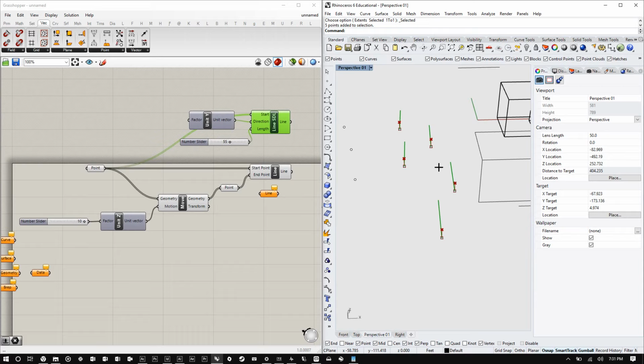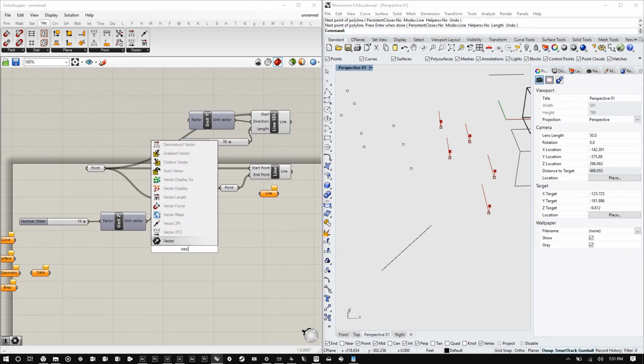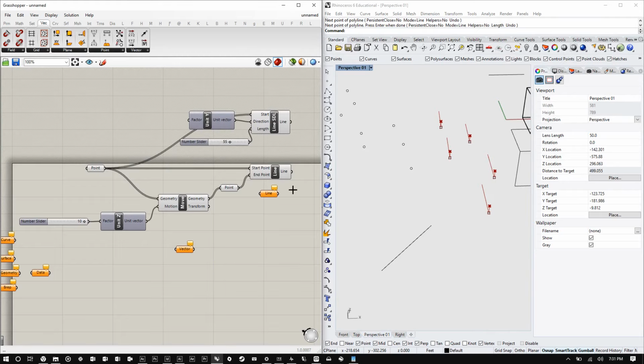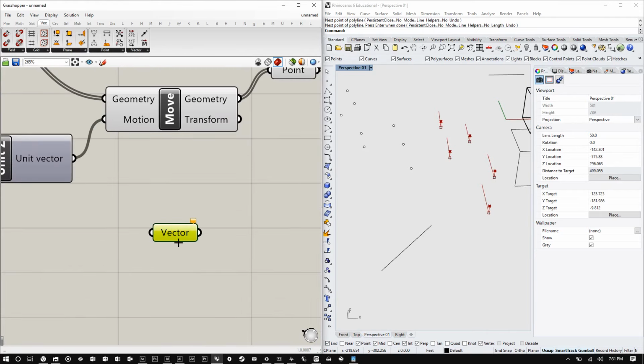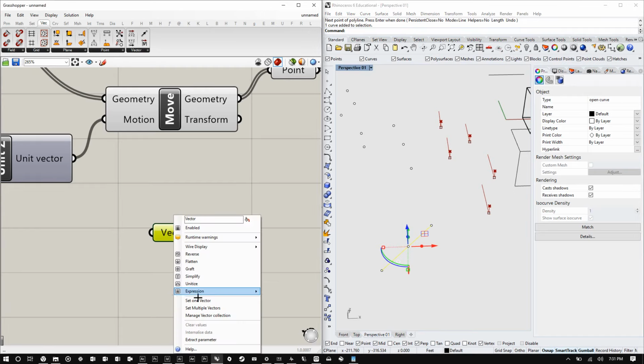Make sense? Okay. Now, this is something that's really cool. Let's say we wanted a direction that wasn't a cardinal direction. Well, vectors can also be considered as directions. So I drew a diagonal line here. I'm going to create a vector component, which is just like all of the other ones. And vectors are lines. Curves, though, cannot be vectors. Vectors are only straight lines because you need a direction. A curved line does not have a direction.